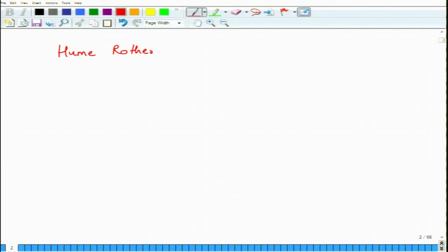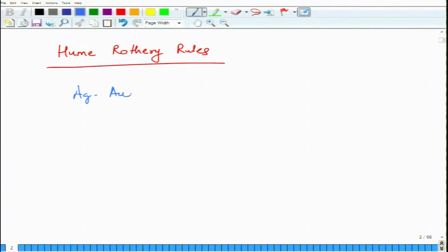There are some rules for substitutional solid solutions, which were called the Hume-Rothery rules, which said that it depends upon the size difference and the valence difference. If you want to make a substitutional solid solution, extensive solid solubility is permitted only when the size difference is less than 15%, the valences are nearly similar, the crystal structures are similar, and the electronegativity difference is very small. There are certain violations, but by and large these rules are followed. The examples which we took were gold-silver, silicon-germanium, and copper-nickel. These are solid solutions basically.